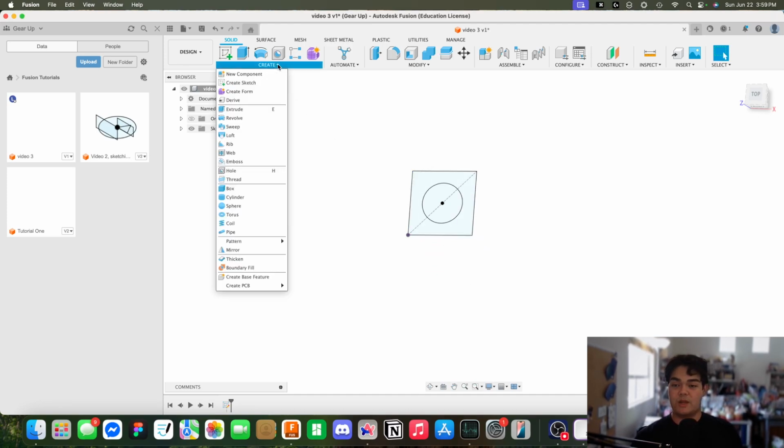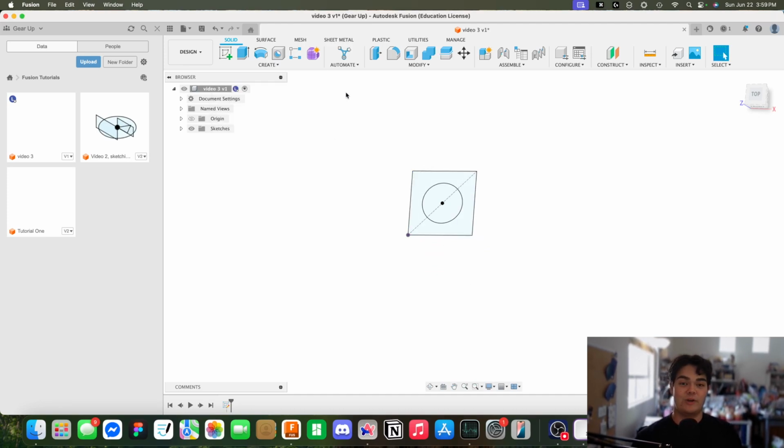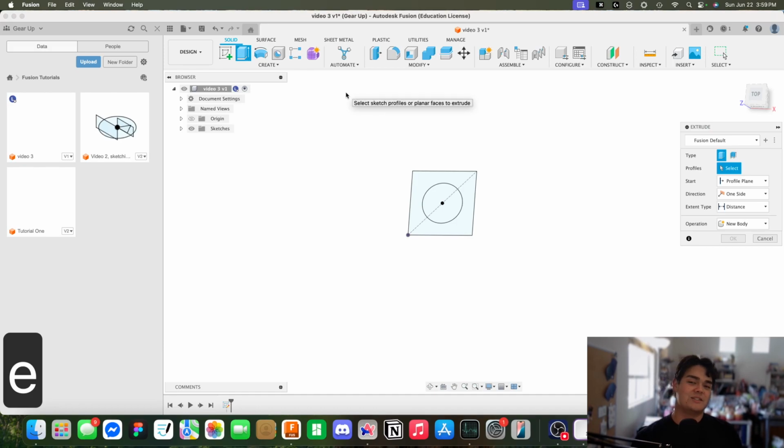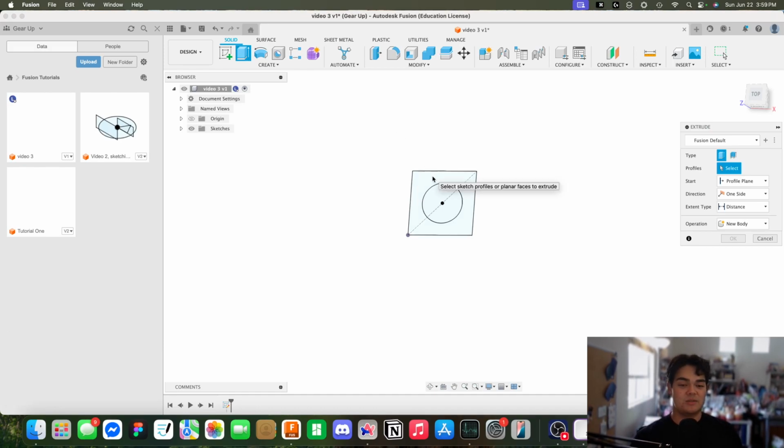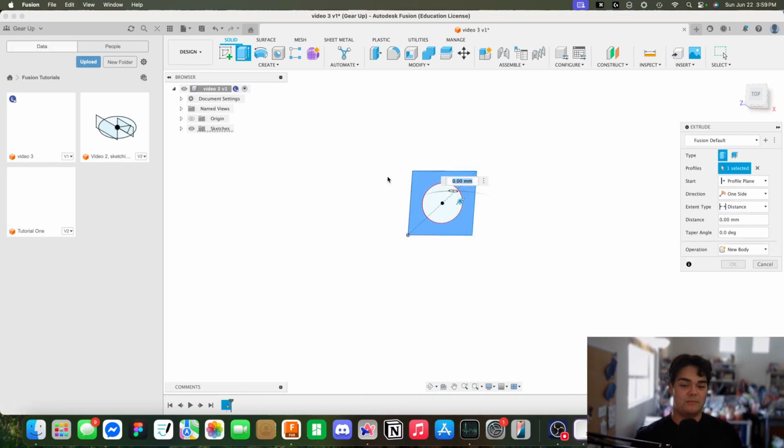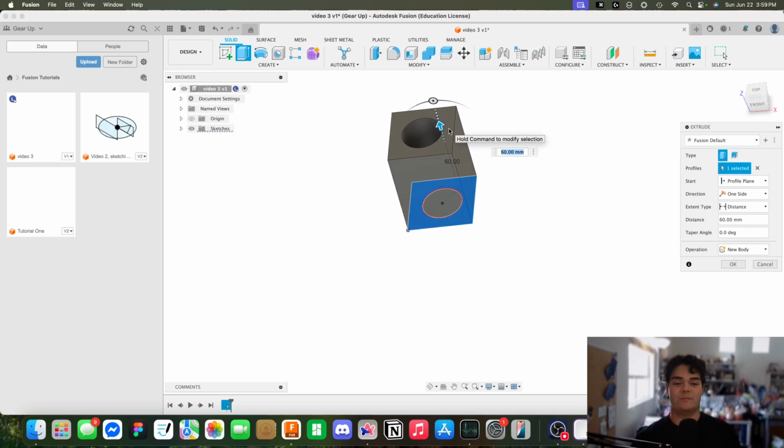So, now with this, I'm actually going to go ahead and create my first 3D shape. We'll go into creating more 3D shapes in another video, but I'd like to do this to show you guys how to make a sketch on a face. So I'm going to go ahead and click right here, this area of my sketch, and this is the extrude function up here. That allows me to take a 2D shape and simply drag it straight out to form a 3D one. You can either drag it out to a distance, you can see the readout here, or you can just type in a number.